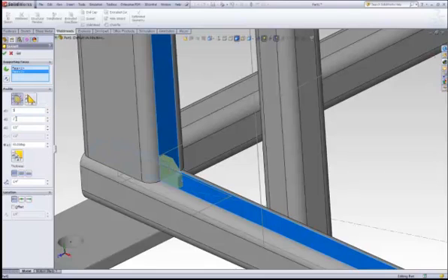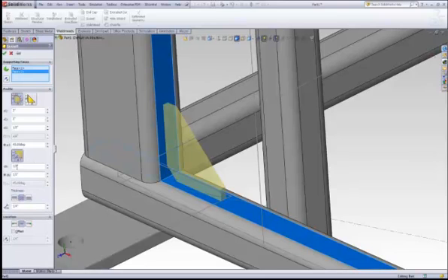You can change the size of that gusset, the location of the gusset to make it centered, and whether it's extruded to one side or mid-plane. And then there's another button here to add a chamfer to the inside corner and apply a size.